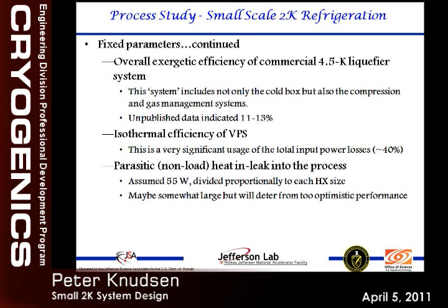As I will show you in a minute, we compiled some unpublished data to get an idea for smaller liquefiers what the exergetic efficiency would be. So in the range of 11 to 13% is what we saw for 2 to 3 grams a second liquefaction. It's worth mentioning too, as you get higher in liquefaction flow rate, of course, the efficiency will get better, as typically they use more expansion stages.